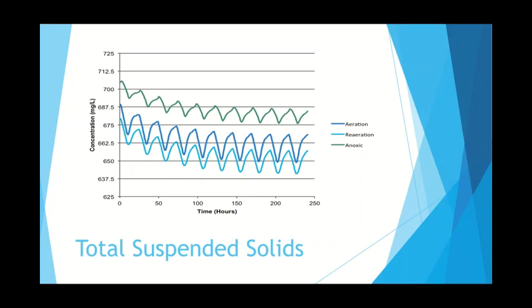This graph shows the total suspended solids in our model based on current plant specifications. According to our model, the plant is not retaining enough of the suspended solids to reduce the nitrogen and phosphorus to acceptable concentrations. The plant uses 60% recycle of suspended solids at the current time.